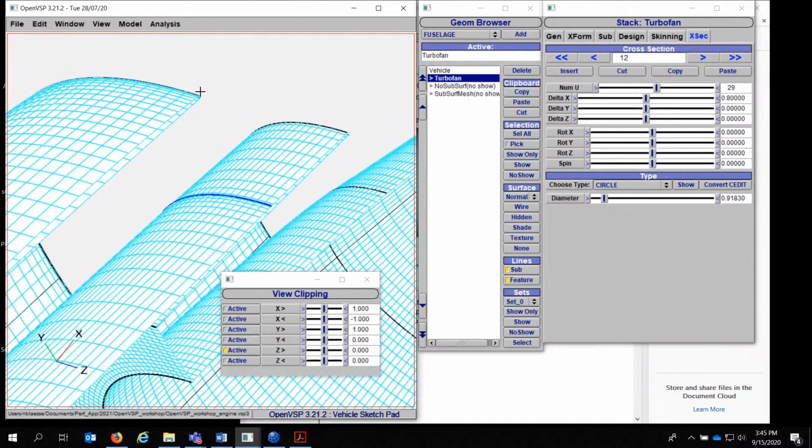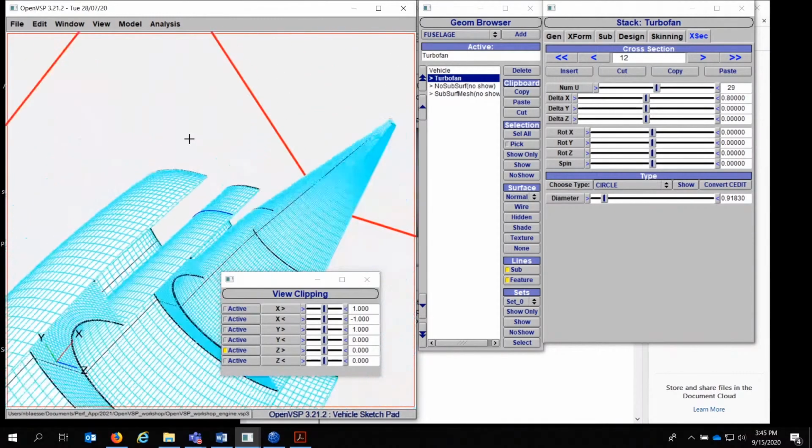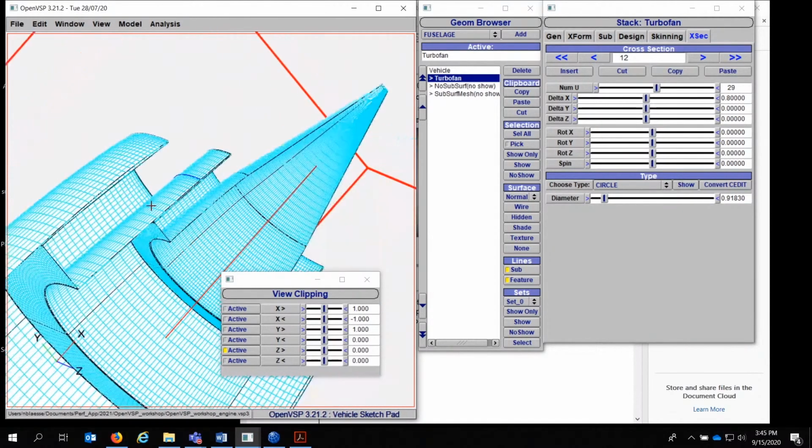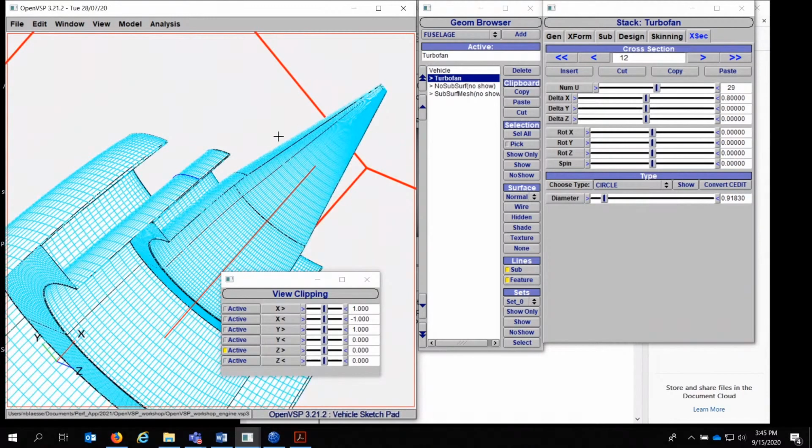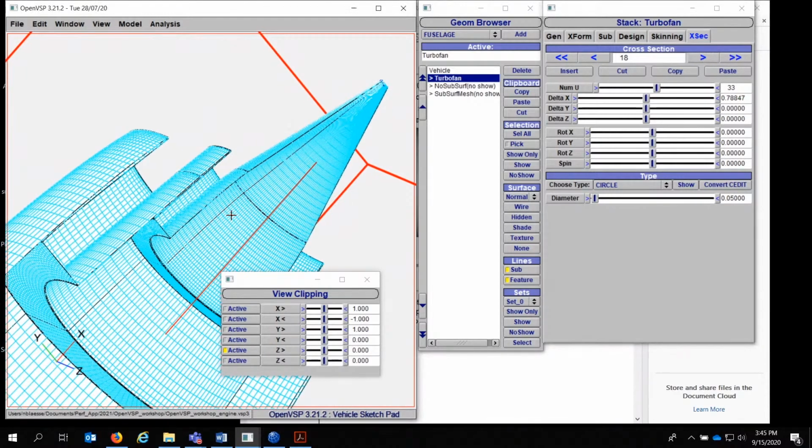And if you're doing some kind of inviscid solver, you really only need to know the area of your boundary condition, so you know how much back pressure to apply there, and then the area of your nozzle, so you can control the Mach number there. And with those two things, you can pretty much set everything up. Viscous solvers are a little bit trickier, but Cart3D was inviscid, so I didn't have to worry about that for a while. And then after that, same process for the core. I put another cross section here to give the core nozzle area. And then I think in the back I have a few more cross sections to pad it, so I got 20.